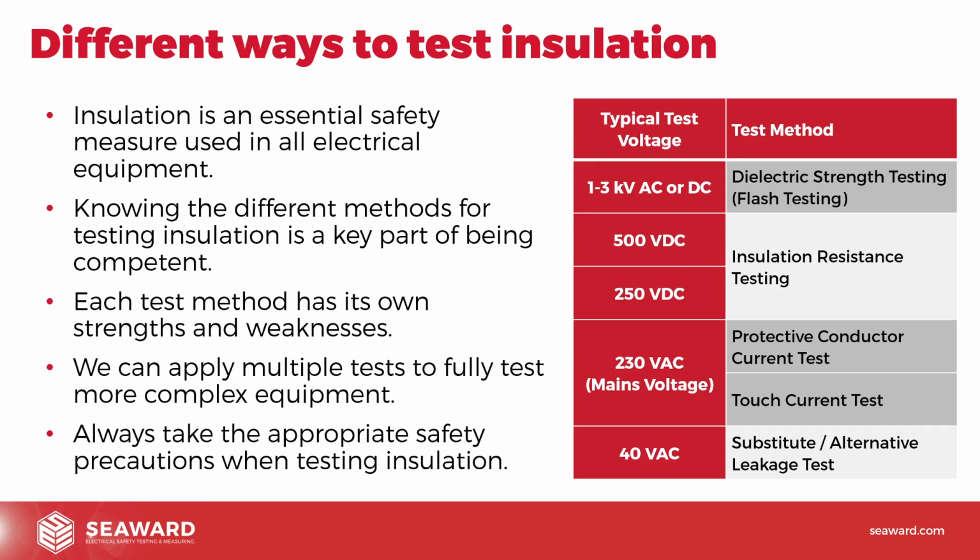We'd normally always advocate carrying out an insulation resistance test anyway before you did a protective conductor current or touch current test. Because what you're doing is checking the input side of the equipment and verifying, at least as much as you can, the safety of it before you carry out those tests.